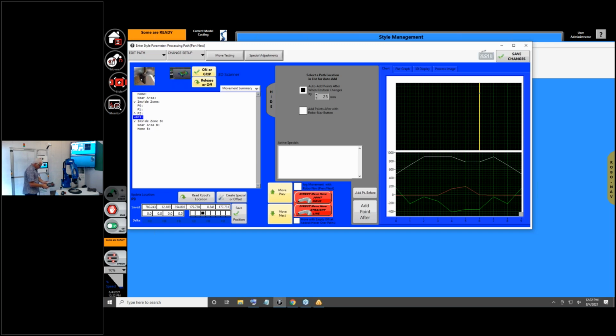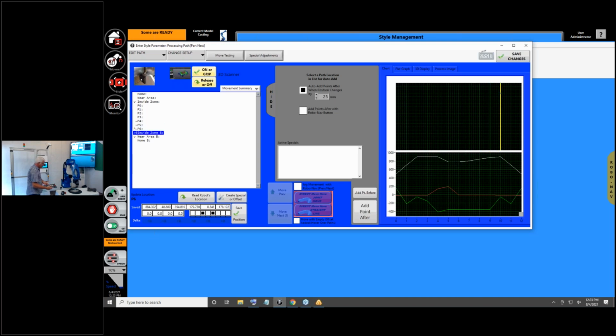So I can now switch back into dependent control here, arm this guy up, and I can move around by hand, forward, up this way, and you can see points being added on the screen here as I'm moving it around. So it's just remembering exactly what I did.